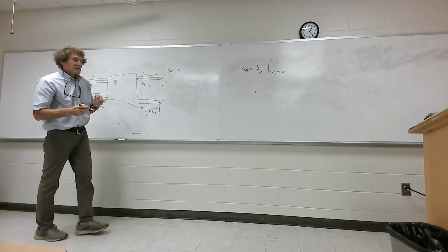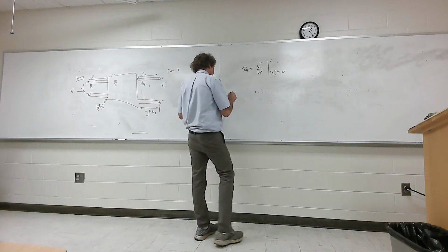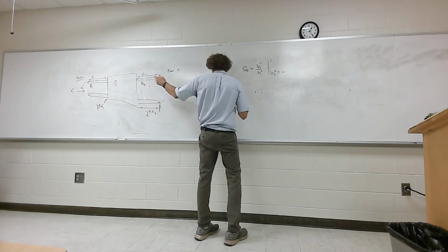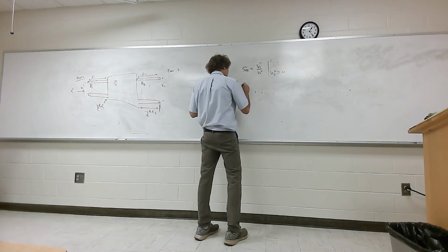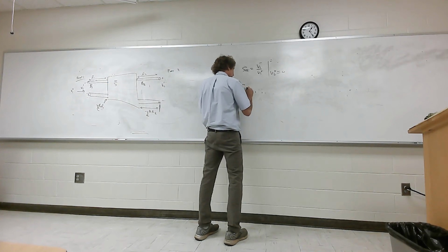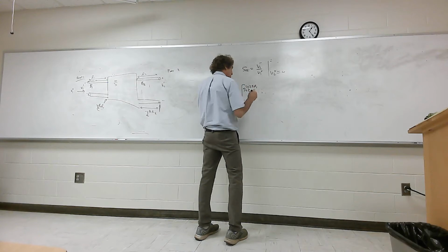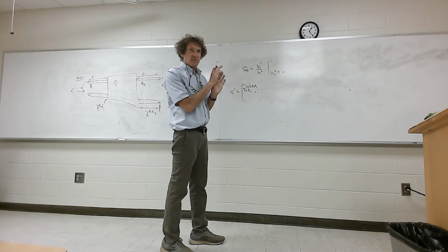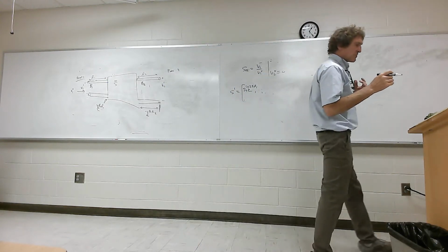So now when I look at the S parameter matrix for the outer point, called S prime, that's going to have S11, and it will have e to the minus j 2 beta 1 L1 because of the phase change involved there. And this is shown in his book.